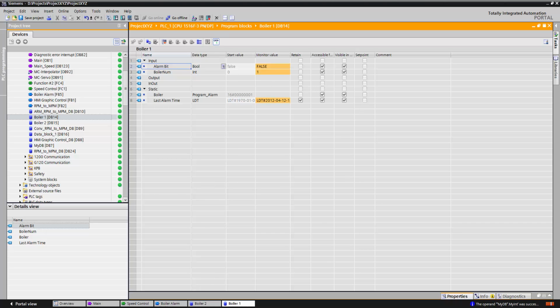And now with monitoring out of the way, I would like to talk about forcing. Forcing is the process in which I can hold the state of an input or an output to be what I want it to be. And despite what might be happening to that input or output in my code or physically to the sensor, it will remain at that one state. I want to emphasize that forcing your variables is a temporary solution.